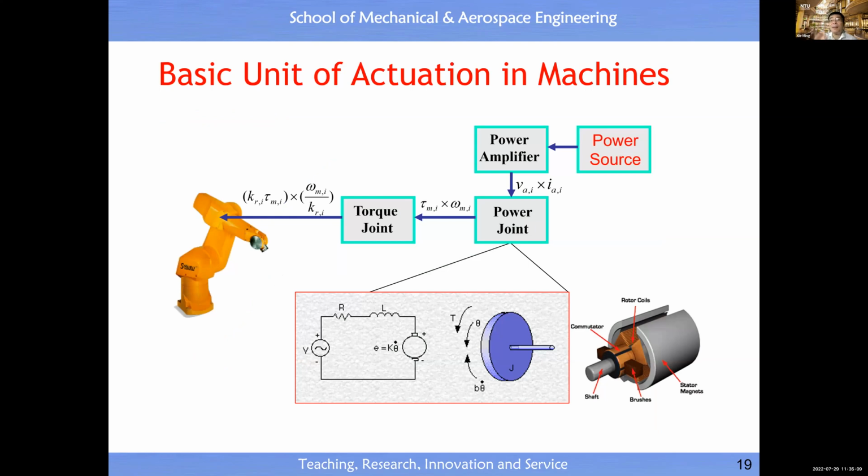Actually, a motor is a mechatronic device. It is an electronic device because it takes electric energy as an input. A motor is also a mechanical device because it outputs mechanical energy. So therefore, it is a mechatronic device. All right. So for the input, you see, this is a circuit. It's very simple. We apply the current which goes through the coil in order to produce a magnetic field. The magnetic field will interact with the permanent magnetic field, then create an interaction force. Then this interaction force will make these two rigid bodies undergo relative motion.